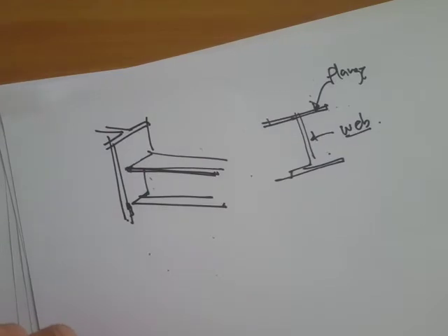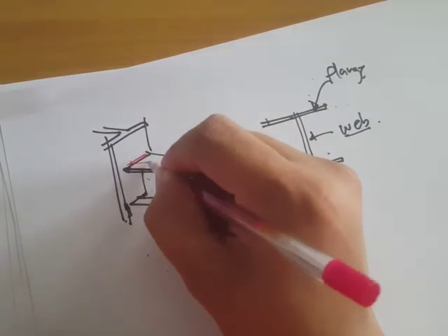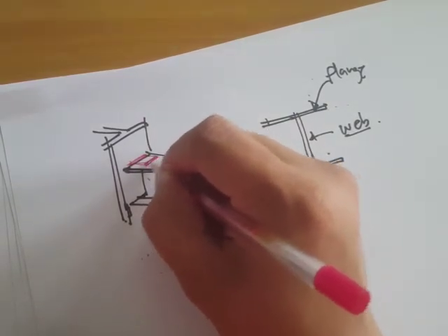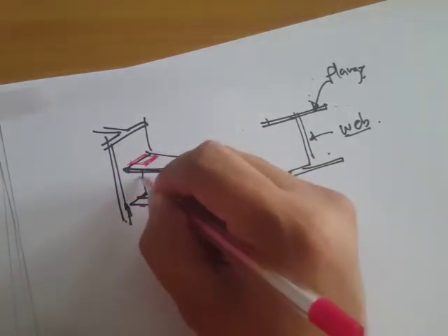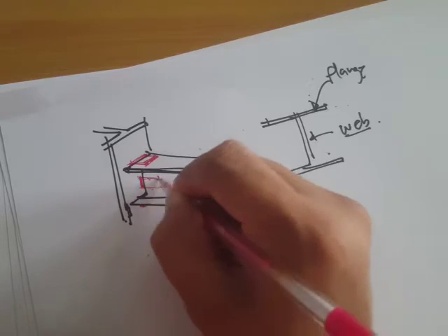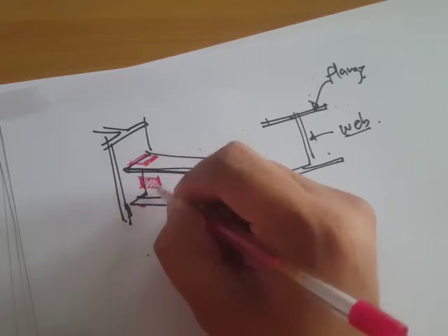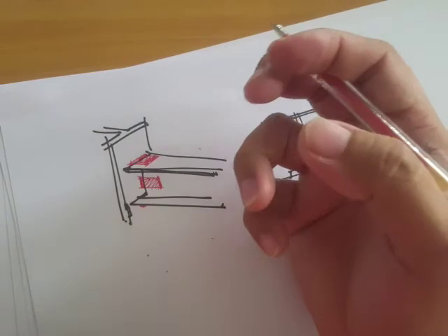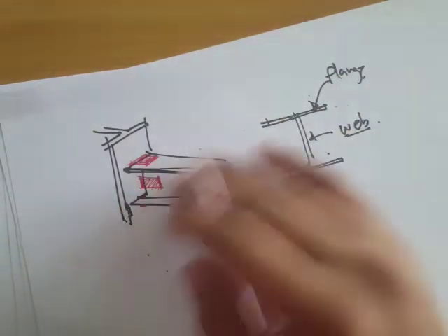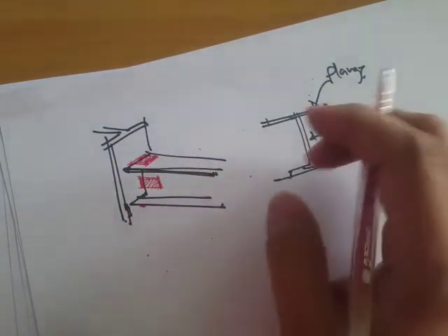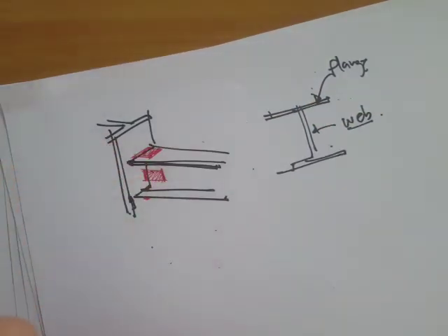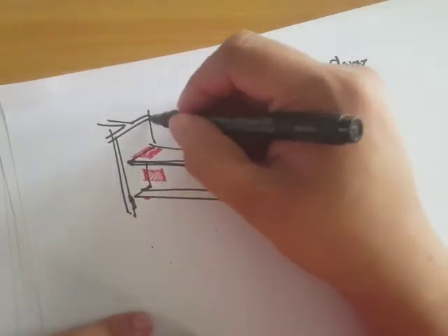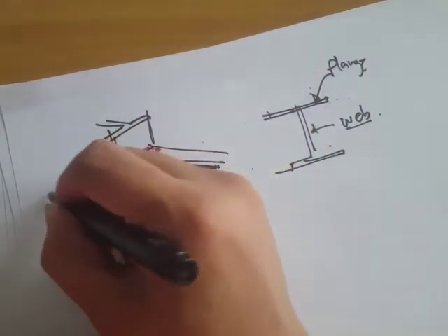If there are extra plates welded on top, restraining this top flange and then the bottom flange as well as the web, let's say extra plates welded to the column and then welded to the beam, then it's actually making a rigid joint. It doesn't allow movements along X, Y, and rotation along Z. So we can idealize it as a fixed support.